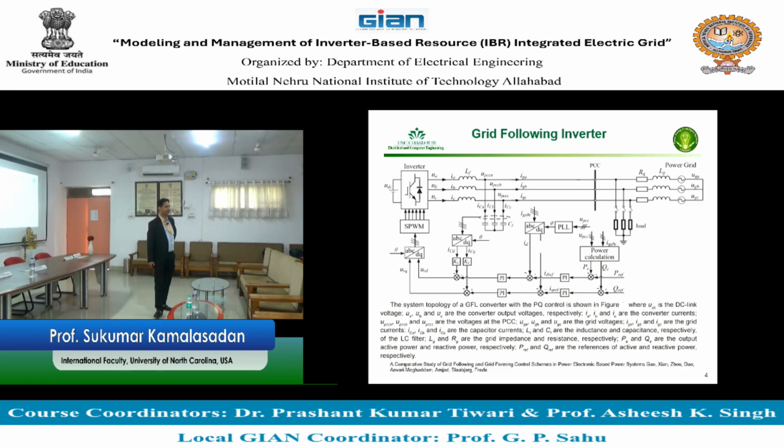Ideally, what happens is the voltage is generated from the inverter based on the operation of the switches. Switches are power electronic switches that move very fast. Because the switches move very fast and because of the switch combinations, the DC input that is coming in will be changed in the form of a step change of DC on the positive side and a step change of DC on the negative side. This is how, and so how fast you operate the inverter, how you do that.